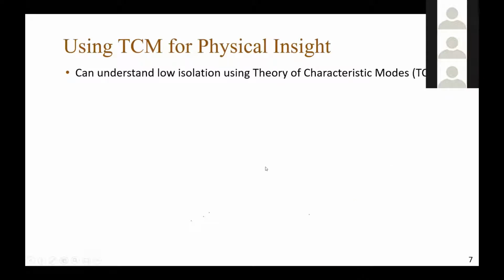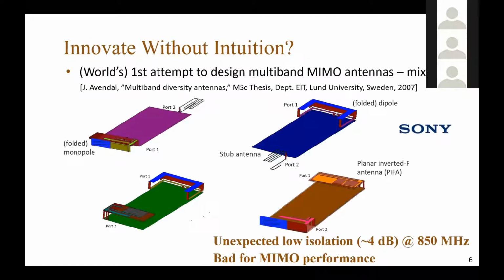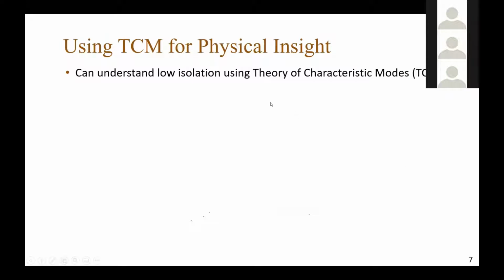So it took us some time, I guess 2 years, to look around and try to find out what the problem behind this was. Now, the issue is that if you were to put two dipole antennas parallel across this terminal, you have still a spacing of about a quarter of a wavelength. We wouldn't expect such poor isolation even for dipole antennas placed parallel with this spacing. So what is really the problem here? We figured out that the theory of characteristic modes can give us the answer.